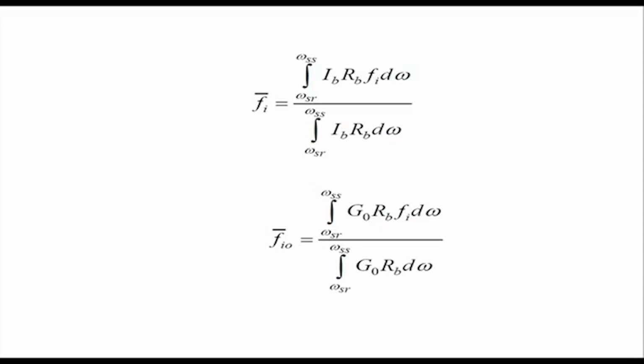And we have the argument that a significant amount of solar radiation arrives during a certain time period like 10 to 2 or 9 to 3, and the rest of it is only 10% or 15% of the total daily radiation. During this brighter period, the clearness index is likely to be uniform, and hence we get the classical result to be quite close, even if you calculate with the data or assumed diffuse fraction and distributions.